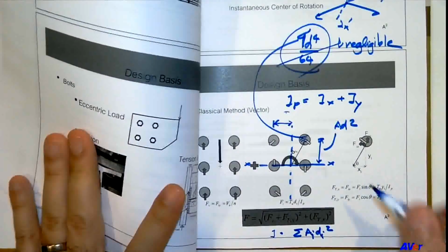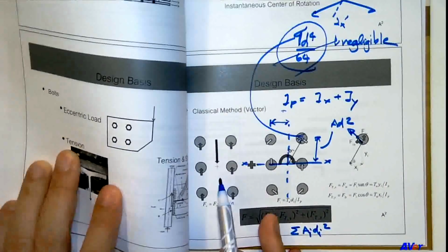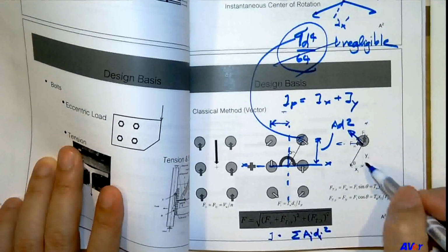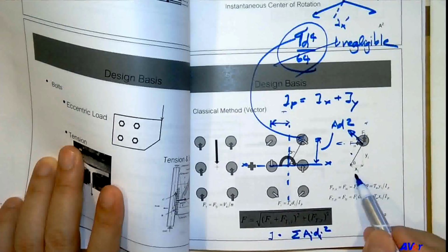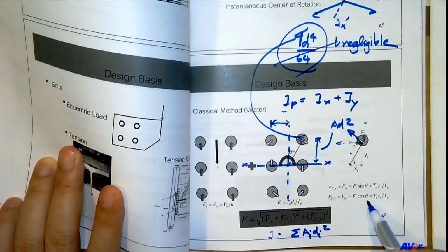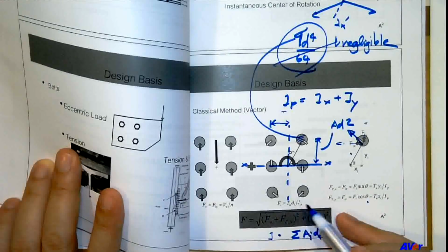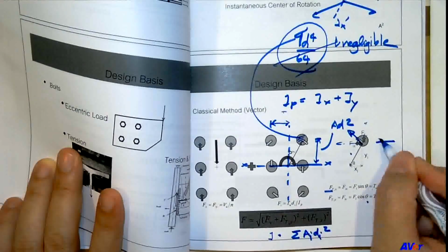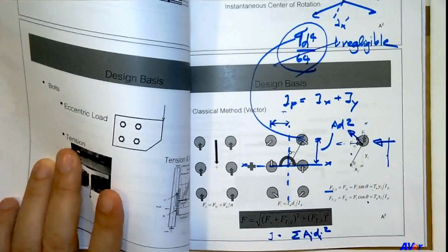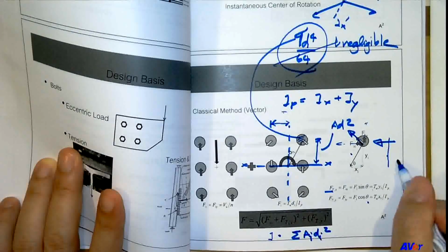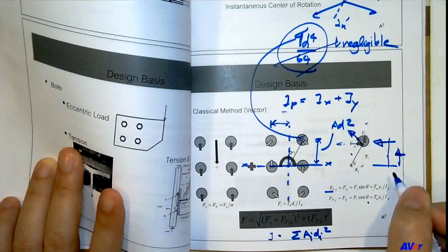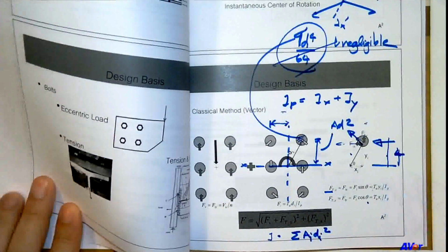So we can come back here, and this is the true force, right? But if we want to sum up the force, we better change the force into the x and y components by using sine and cosine. The sine term is y over d, where d is this moment arm, and cosine is x over d. So if you multiply sine and cosine into the equation here, you see that the d term will be cancelled. So you have the force in the x component equal to the torque multiplied by the moment arm in the y direction and divided by IP. And it makes sense, because if you have the force in the x component like this, to have torsion you should multiply by the moment arm in y, right? If you have the force in the y direction, you should multiply with the moment arm in x. Otherwise, you cannot cross the vector. All right?